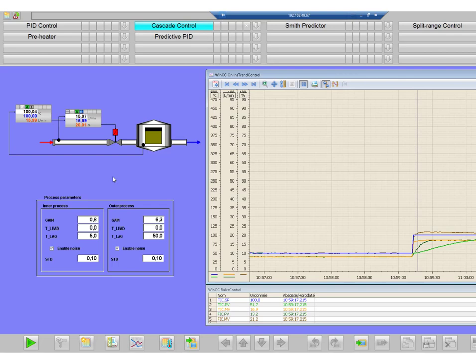We have seen in the slides that you could run filtering and control operation at different cycle times. Another application of different cycle times lies in cascade control. I will not go into the details because cascade control is dealt with later on in the course. It suffices to say now that the internal loop that you see over here, or the slave loop, has a much faster dynamics than the external or master loop.